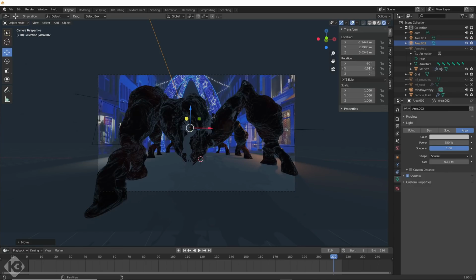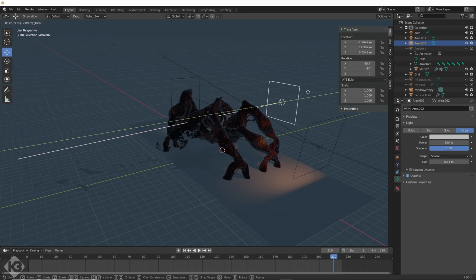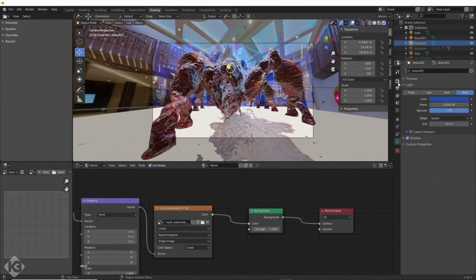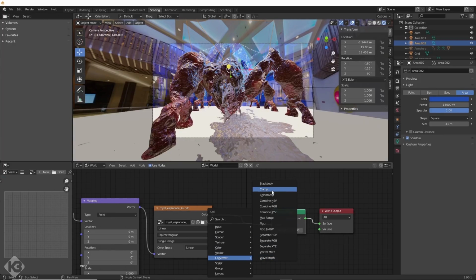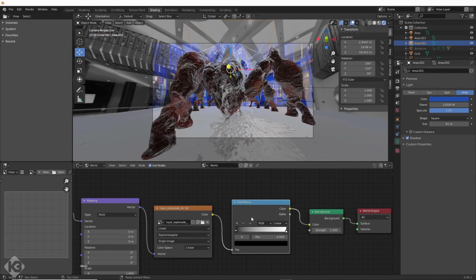It's not optional, but it works if you work it. I think I also added a light above. Next, I wanted something to reflect in the monster and slime. I chose to wrap the scene in an HDRI image that loosely matched the business of this scene. I then changed the colors of the HDRI to match the colors in the background plate. I wasn't concerned too much with the lighting, but wanted something to reflect. It's super fake, but seemed to look decent and add a tiny bit of fill light and reflection.